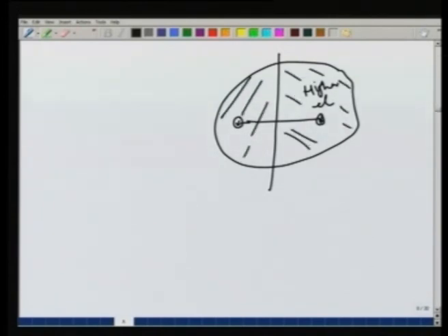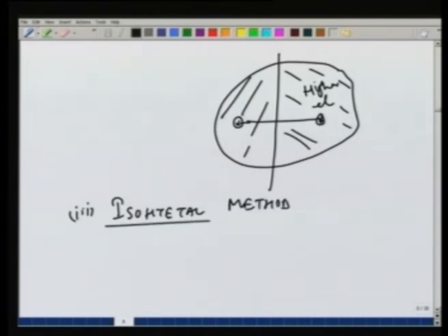It will not account for the topographic variation and therefore, rainfall variations within that area. So, the third method which we use accounts for this possibility also and it is called Isohyetal method, in which we use the rainfall values at each station also in dividing this area.